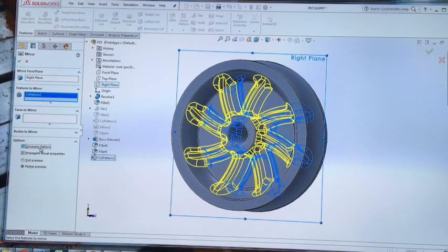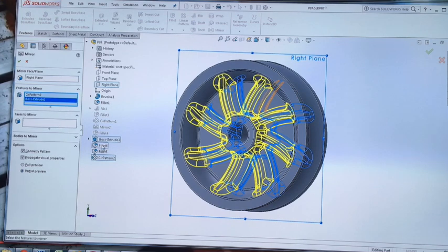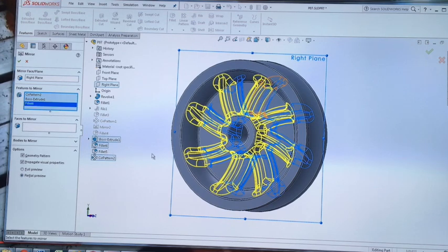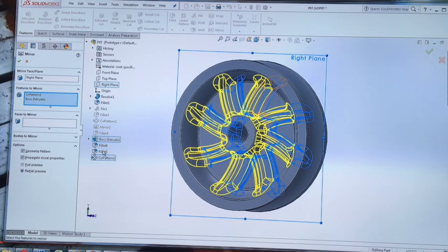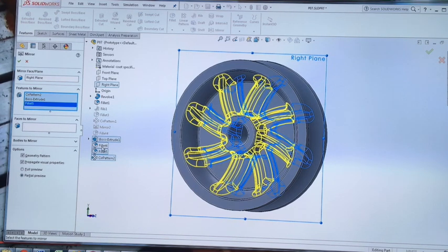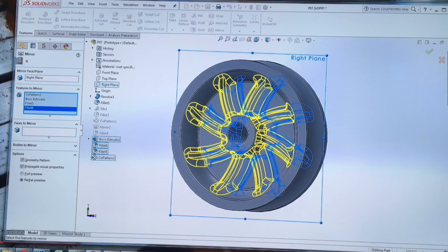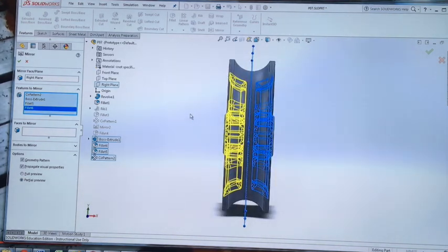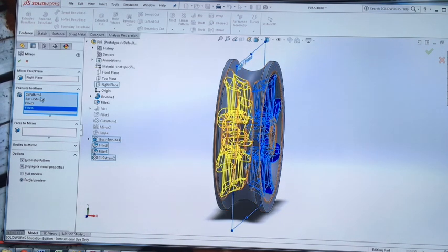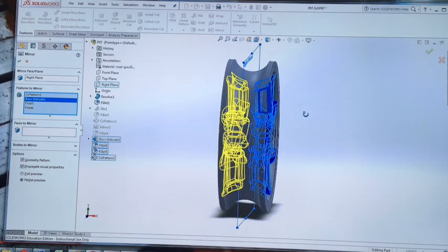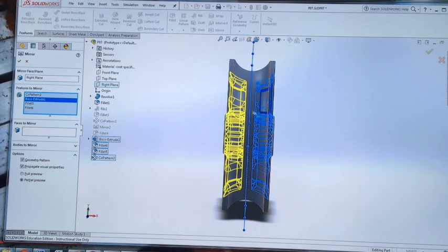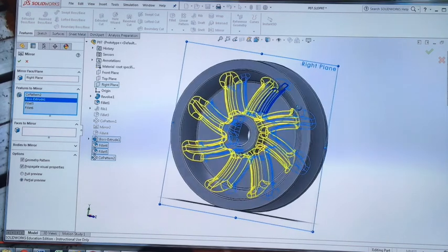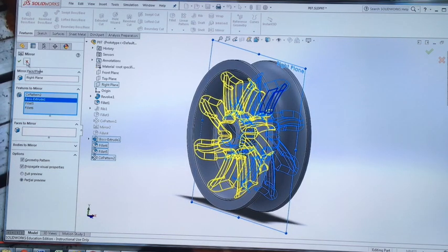Now what I might have to do here is select the original, sorry, this is where we've got into some limitations. So this is the limitation of the extrude up to next feature. Instead of using the rib feature, we use that boss extrude going up to the next body. We're not able to mirror that because it's trying to extrude up to that same body, potentially.